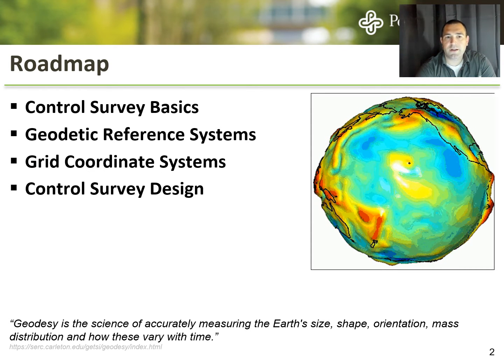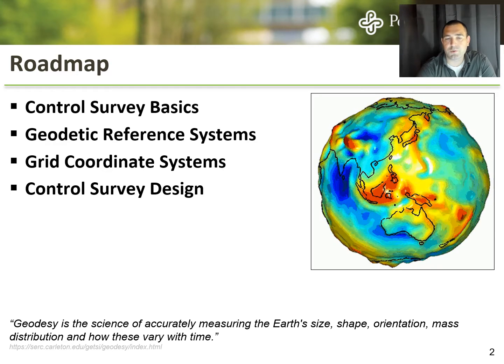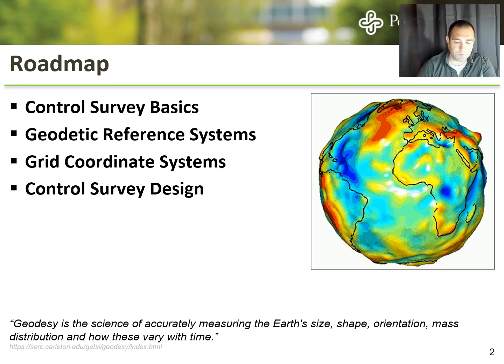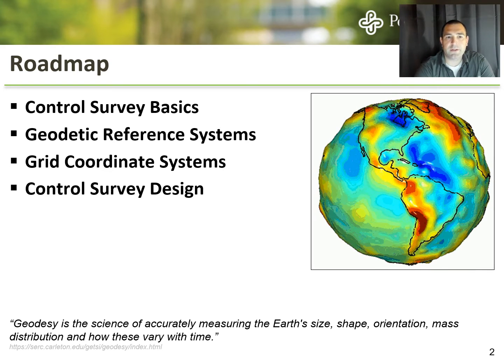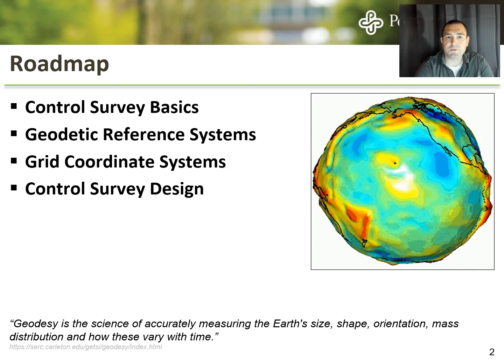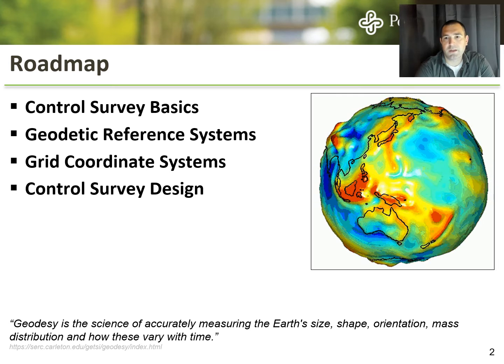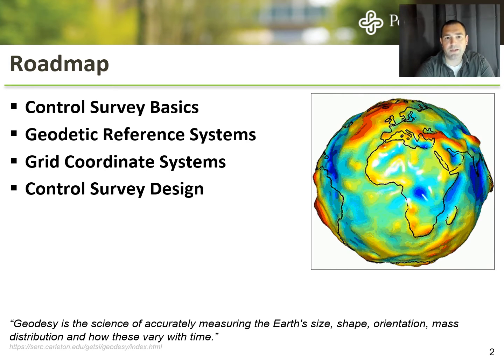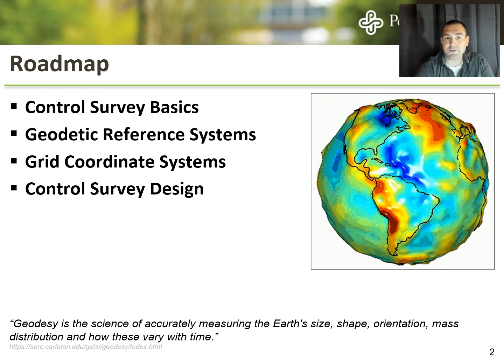So we're going to talk a little bit about the basics of control surveys, or survey control, I guess is often called as well. We'll talk about geodetic reference systems versus grid coordinate systems. They both serve a purpose, but we primarily focus on grid systems in engineering work.